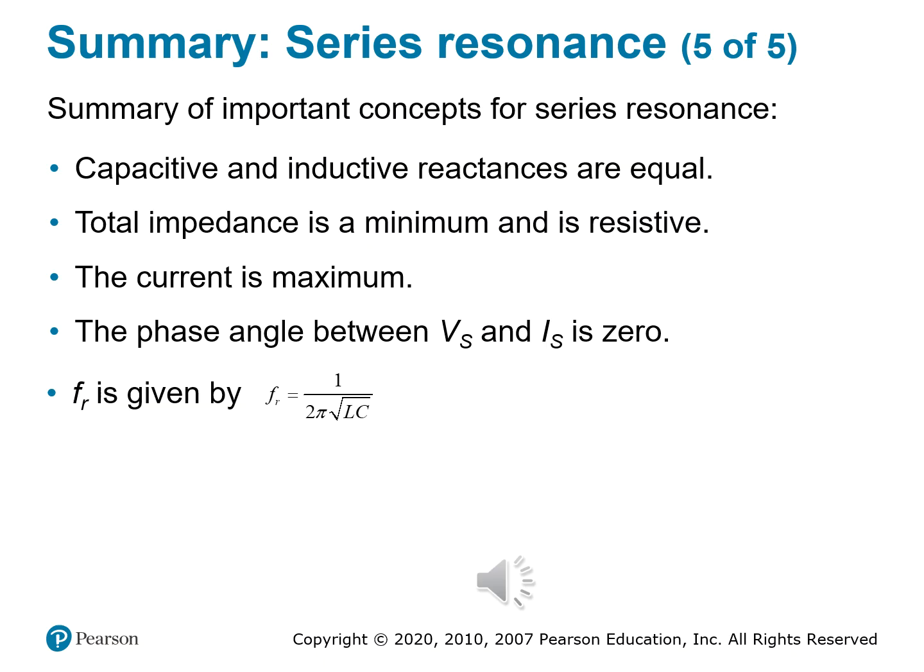So first, this is where capacitive and inductive reactance are equal. Think of them like two dancers with opposite steps. They cancel each other out. Second, that cancellation drops the total impedance down to its minimum. And so what you have left is pure resistance. We're hoping to get the impedance down to 0. That way you're dealing with a pure resistive circuit, and all the energy from your source can now flow freely.